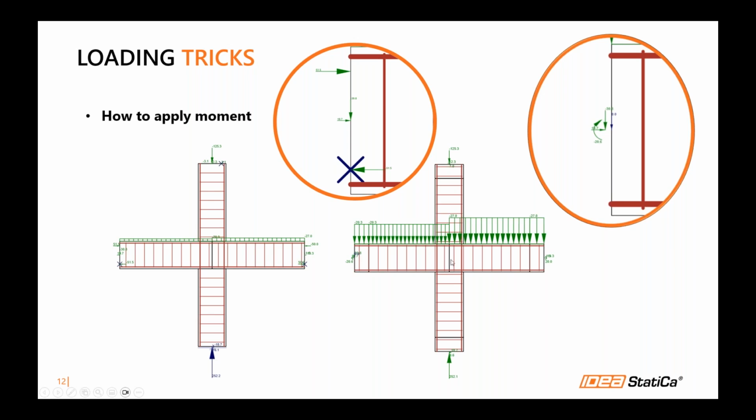We base the calculation on equilibrium, and you basically input the internal forces at all ends, and then just the line loads to modify the shape. But when you model it from walls, you need to set some support. It shouldn't matter where you input the support, when you input the rest of the forces correctly.